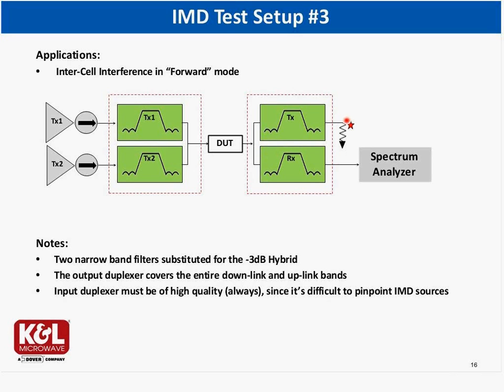Next question: what is the source of the 2.2 dB per dB as opposed to the theoretical 3 dB per dB? Doesn't that significantly change the calculation? These are empirical values that I gathered from experience when dealing with test setups that are based on filters.